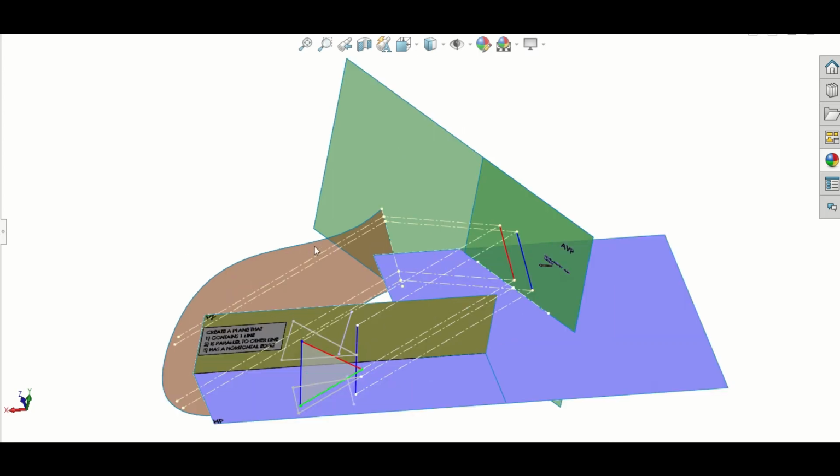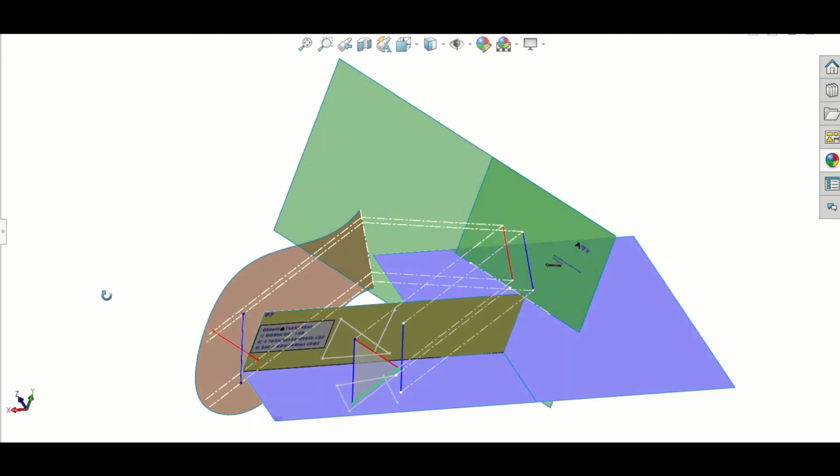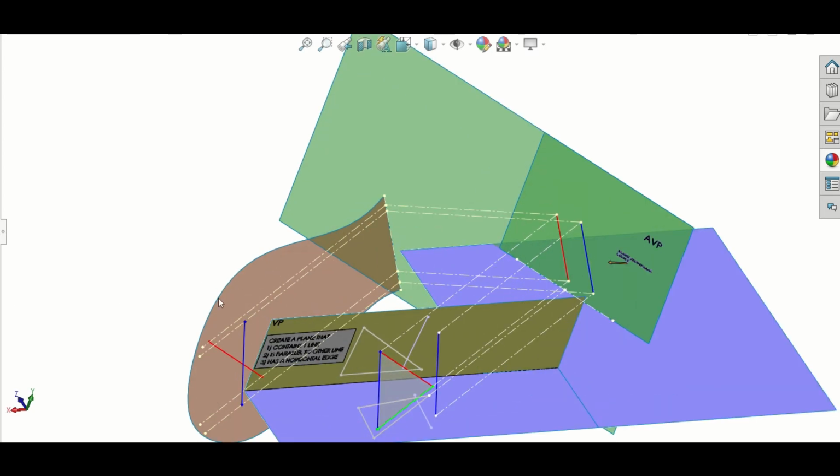What happens then? We project out along the plane, and we take our distances back to the red, back to the blue. Where did those distances come from? Well, don't forget, if we were looking for the distances out to this view, we will always skip one view and work back. Why does that work? Well, watch this.